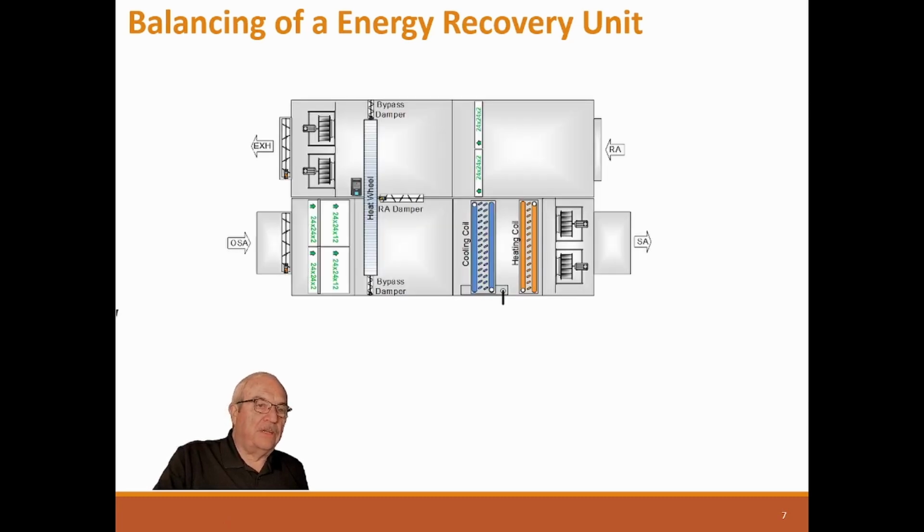So now let's look at an energy recovery unit. An energy recovery unit, this is an air handling unit, is similar to the simple energy recovery unit, except they're large. And these are normally used for large systems as DOAS units, or systems that require a lot of exhaust air. These can also be used for large zones like civic centers, basketball courts, sports arenas, things like that, that require a whole bunch of outside air. Because these units have 100% makeup air and 100% exhaust air, there's 100% across them.